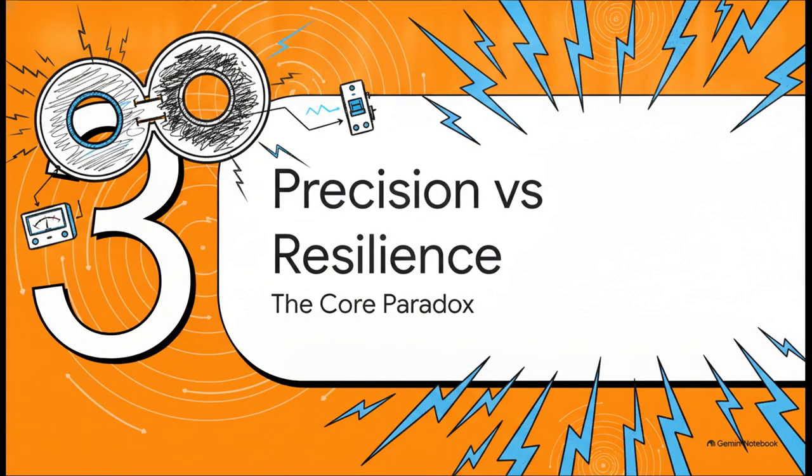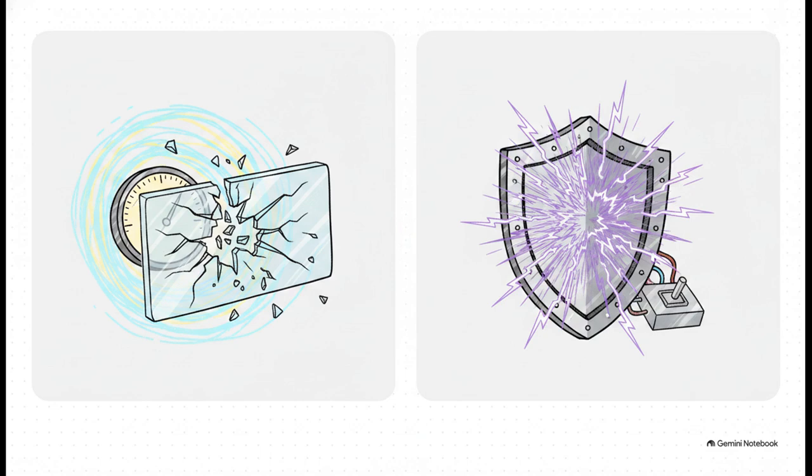Well, that brings us to Section 3, the paradox of precision versus resilience. And this is a truly fascinating engineering hurdle. The different instruments attached to these separate secondary cores have completely opposing needs, especially when a dangerous power surge hits the grid. Measurement cores, like your class 0.2 or class 0.5 cores used for ammeters and energy billing, they actually need to fail, deliberately. We call it early saturation. If they don't tap out early, a massive surge will literally shatter the delicate billing meters attached to them.